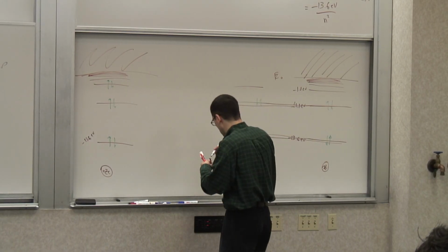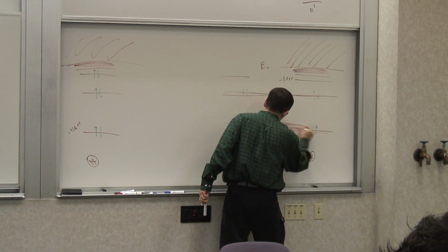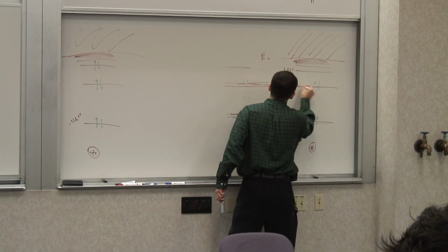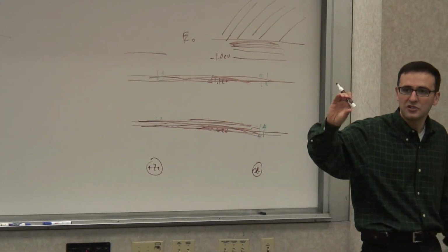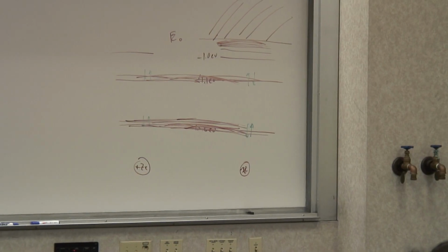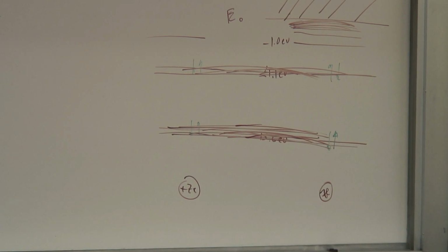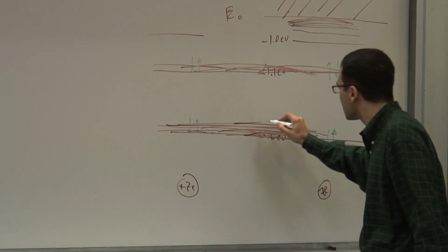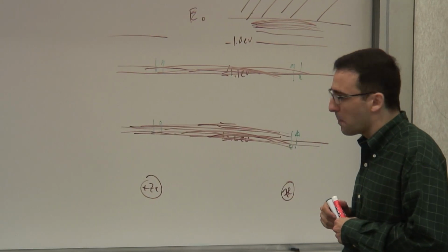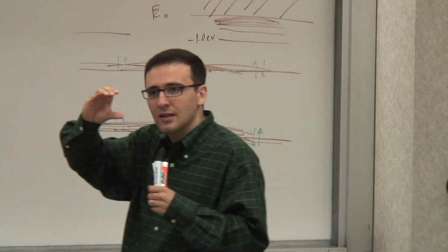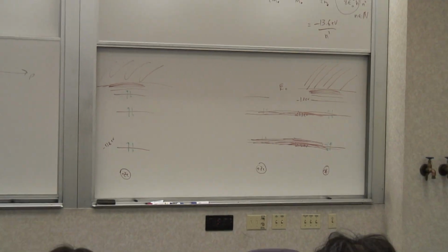I expect there to be so many energy levels within a range, right? So there will be multiple energy levels here and multiple ones here, to the extent that at some point there are so many of them that for all practical purposes I can say there's an energy band. There are so many of them that you say, well, this is an energy band. Within this range of energies, I have many, many levels with such and such density of states. So that's why you have energy bands in lattices, when you have multiple atoms, instead of individual energy levels.